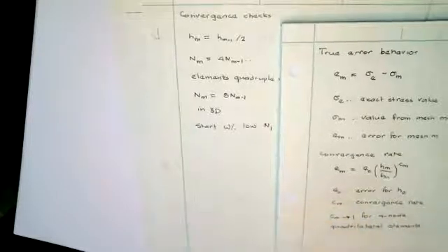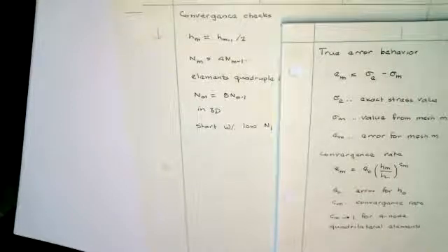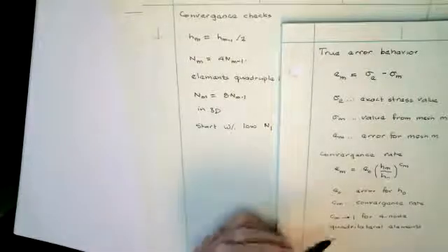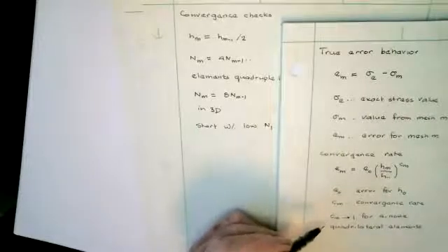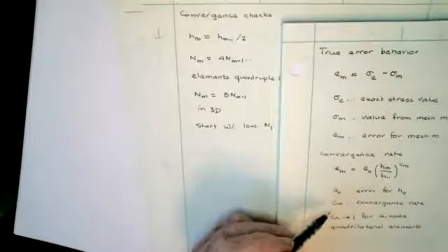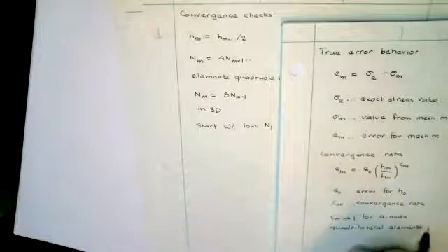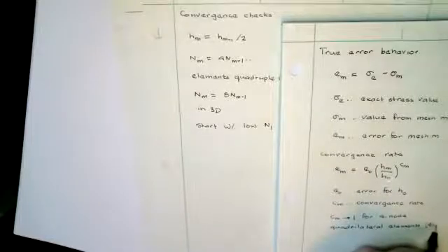if we have 4-node quadrilateral elements, then your approximation function for the stress is essentially a constant. It's got one linear term, but it doesn't have the complete terms. So it's missing linear terms. So the parts that are missing give you the dominant error, and they're linear. And so you tend to converge linearly. What does that mean? It means you halve your mesh size, you halve your errors. Okay? We're going to abbreviate these elements as 4Q.